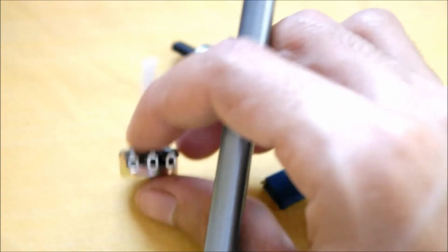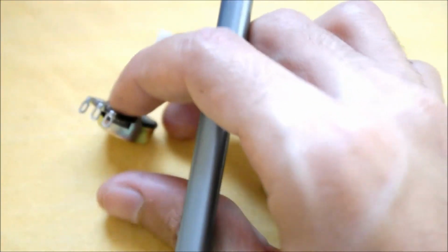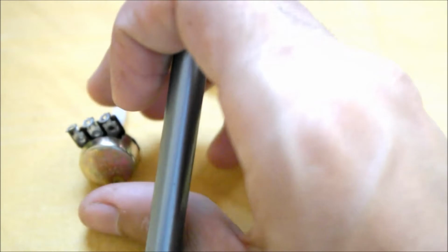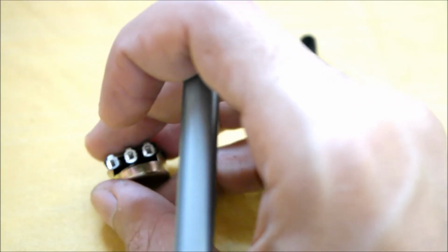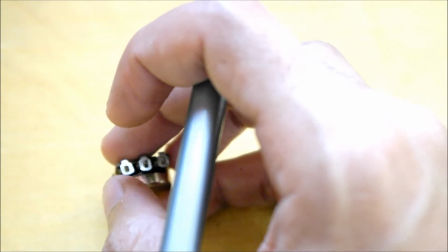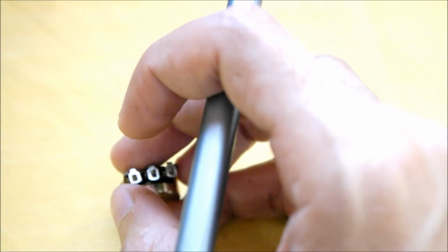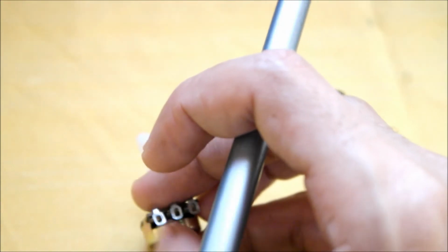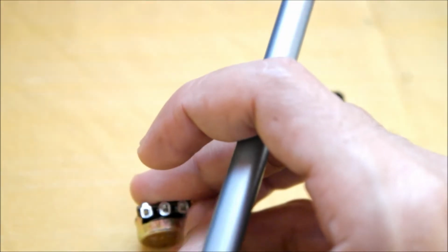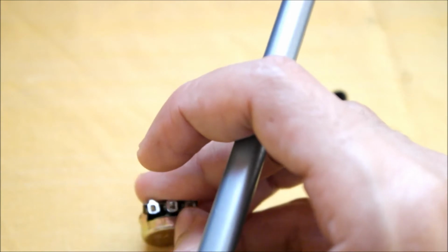But how to check them? Again, to ensure that their values are perfect or not, you get your multimeter and poke one of the terminals. As I said, resistors are unbiased, so don't worry about which probe goes where. Just put any probe on any of the terminals. These are the two extreme terminals. If you notice, you have 3 pins here.